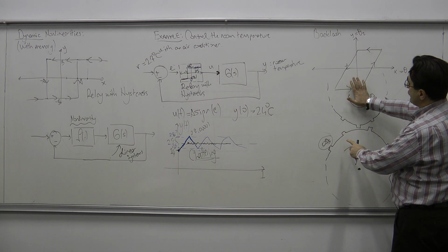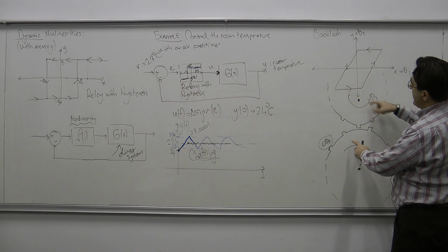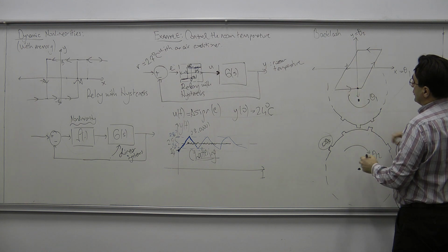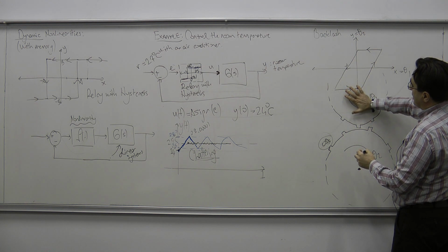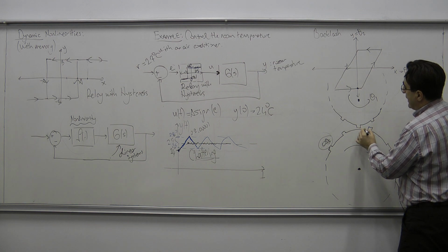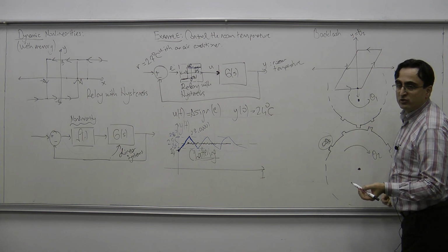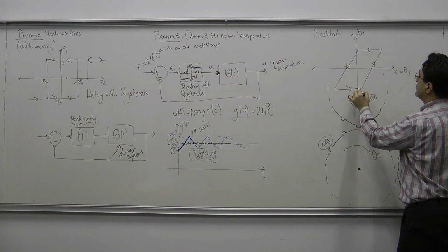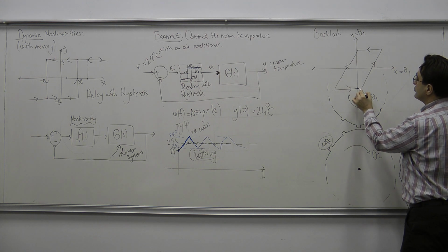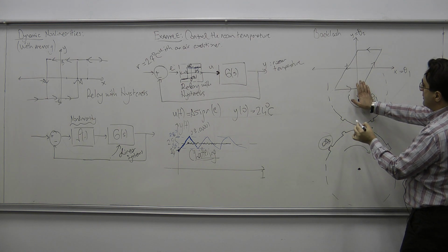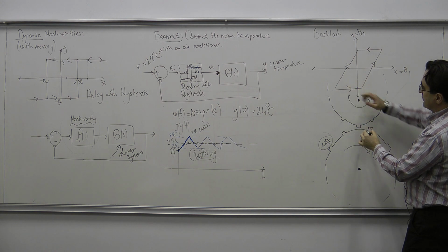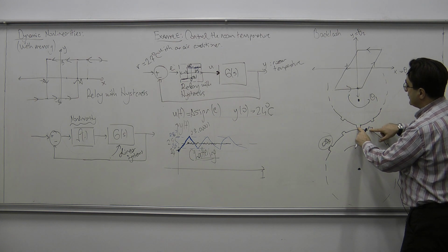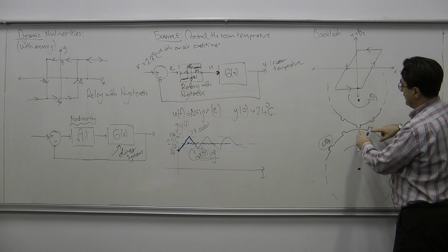So when I turn the gear with angle θ1, suppose that we are here. When I turn this first gear a little bit, I see that these two cogs are not going to touch each other immediately. So θ2 is not going to immediately increase from its value. It's going to remain constant for some time when I increase θ1. So this θ2 is going to remain constant until these two cogs touch each other.